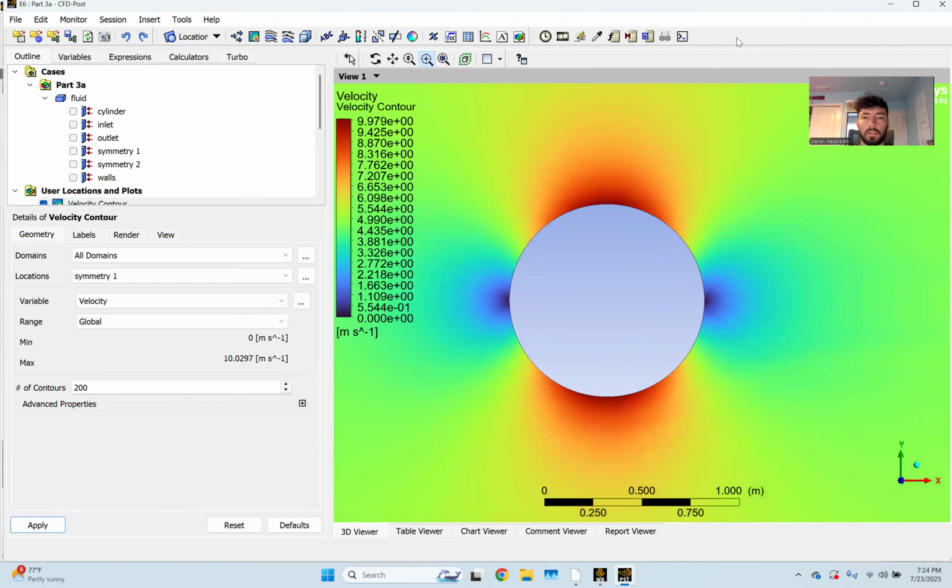And unfortunately, if we did decide to plot the velocity variation on the surface in CFD-Post, we would get 0, like a simple straight line, which is not good in our case. It would be if this was a viscous flow, but this is inviscid, so it wouldn't count, which is why we have to export all of our data from Fluent and not CFD-Post.